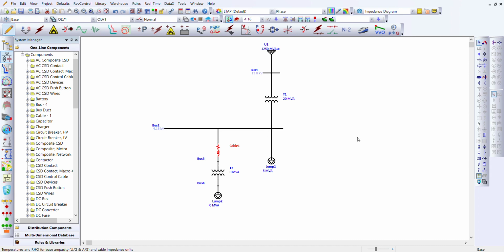So we search for NEC. Oh yeah, this is NEC. But this is 1-core, so it won't work. It's supposed to be 3-core. 60 Hertz, copper, correct. 5.0 kV, correct. Percent phase should be 133, correct. Number of cores, 3 cores, correct. EPR, correct. NEC, correct. Magnetic, correct. So we've gotten our cable.